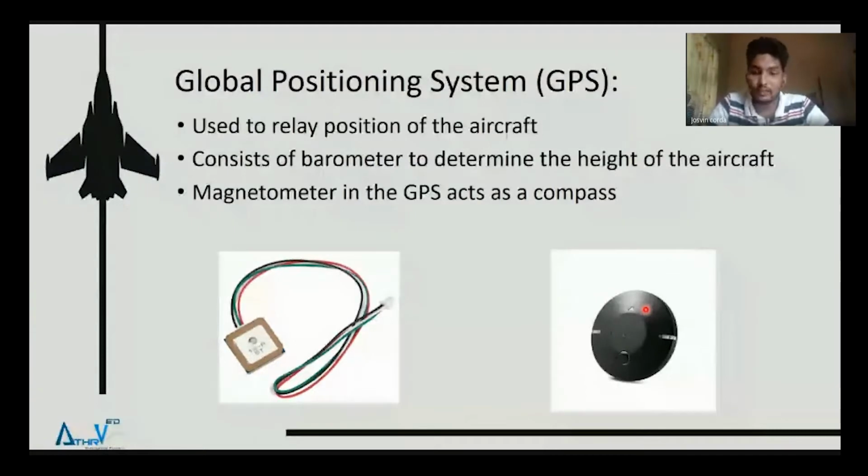This is mainly because the GPS can be placed fairly far away from the aircraft, at a certain distance, so it does not cause interference, like electromagnetic interference or sound, or the changes in air pressure due to air moving over the aircraft. The GPS is mainly used to track the location and send the information to the flight controller.